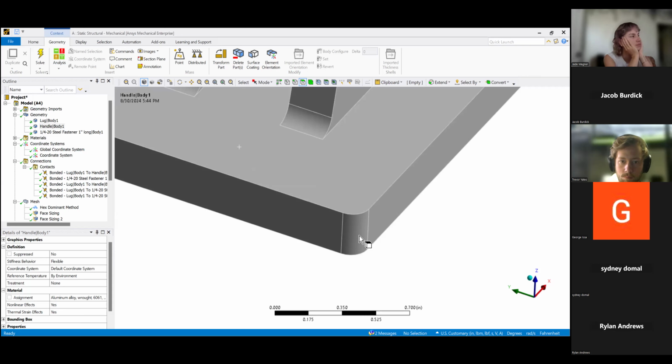There is. I think it's done through the CAD software that's built into Ansys. I think you have to go there and physically add material, then go back to your study, and the material will be added and you can solve it that way. But from the study directly, I don't think you can add material to your mesh.